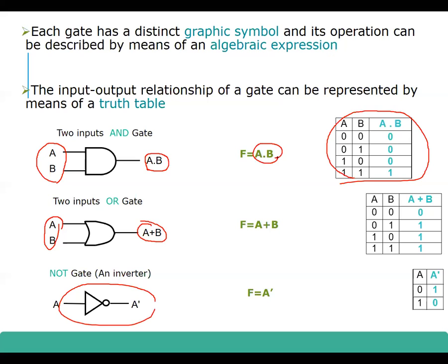When the AND operator is applied, you can see 0, 0 is 0 and only 1, 1 is 1, mainly because ANDing requires both to be considered. A and B both need to be true to get a true output, as the English meaning also suggests. OR, as the English term means, is when either A or B is 1, then the output will be 1. And in the complement, whatever the input value is, you'll get the complement of that value.